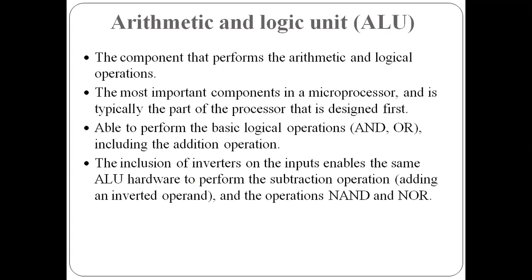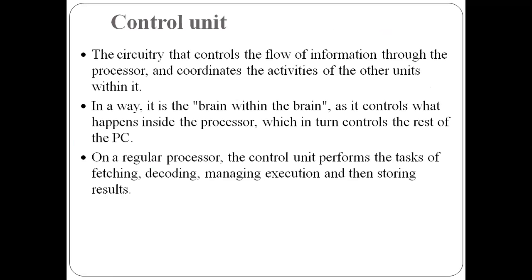Arithmetic and logic unit: the component that performs the arithmetic and logic operations, one of the most important components in a microprocessor and typically the part of the processor that is designed first. It is able to perform basic logical operations like AND, OR, NOT, NAND, etc., including the addition operation. The inclusion of inverters on the inputs enables the same ALU hardware to perform the subtraction operation, that is, adding an inverted operand, and operations like NAND and NOR can also be handled.